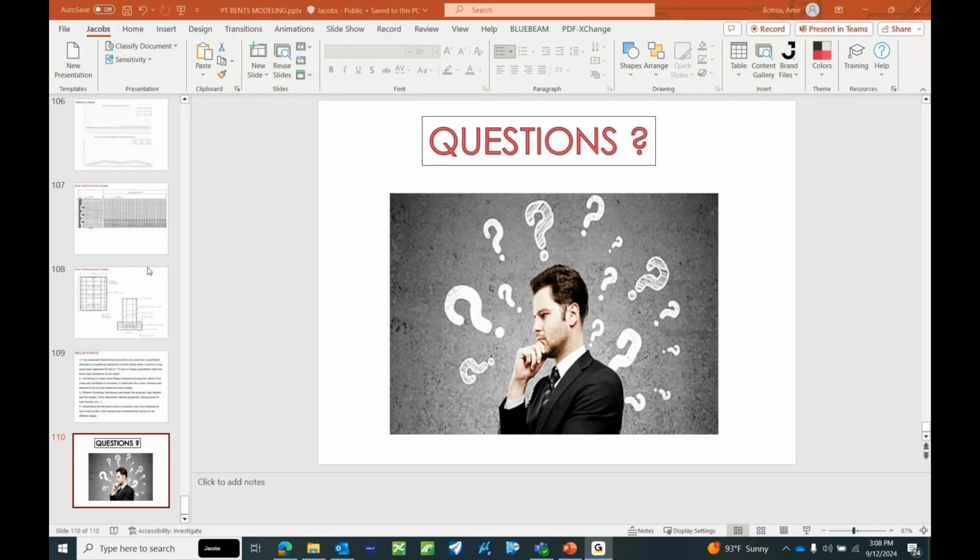And then basically we define a load stage after that. Let's say, for example, the one that I was calling post-tension number one. In this load stage, I activate tendons, let's say 1, 3, 5, 9. So the way that we define it, those tendon groups are going to be active in this load stage. So whenever we activate the load stage later in the construction stage, the program understands that those 4 tendons are active in this stage.